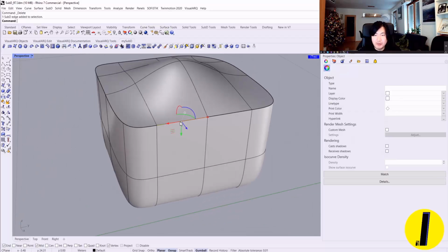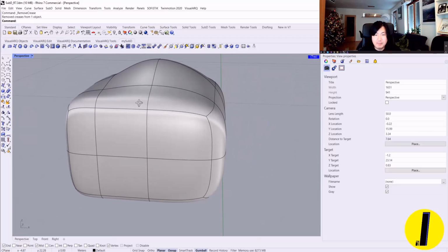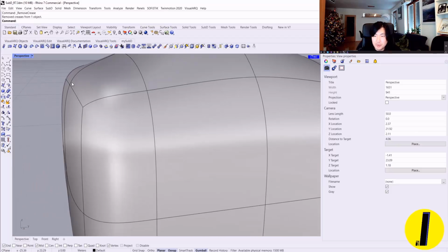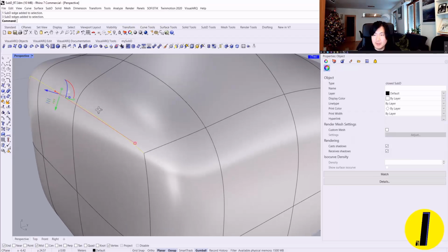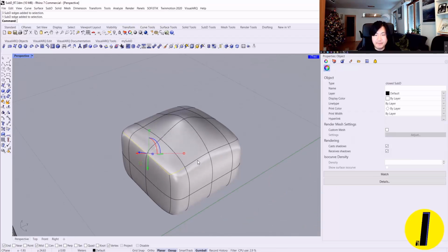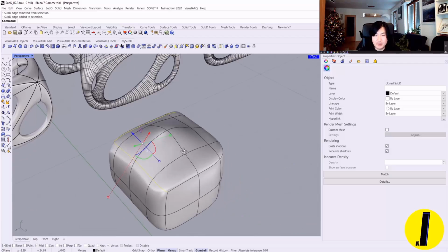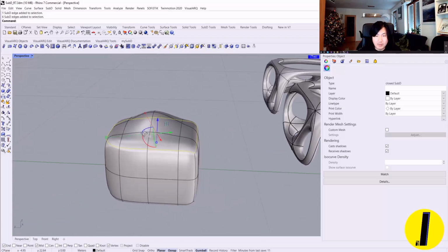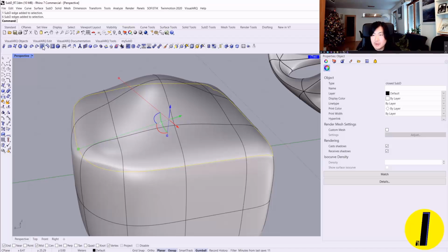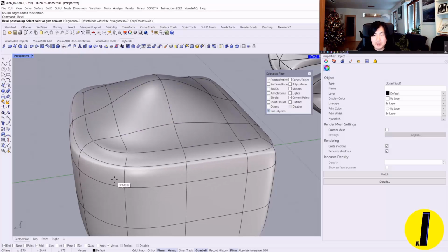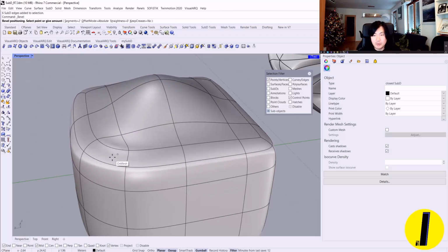Perhaps, yeah, I'll reduce here, remove the crease, but this time I want to have another effect instead of this too smooth. I'm going to select this edge loop, and we can use the command called Bevel. Let's see where it is. Here we go, Bevel Mesh, which means we can give the bevel in both directions.